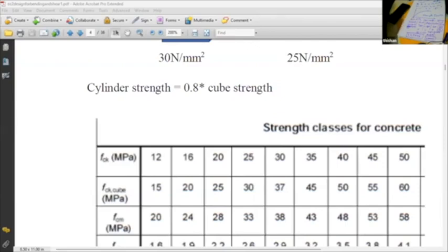Pre-stress concrete are thin sections, whereas reinforced concrete are massive sections. So in reinforced concrete construction, you can use fly ash, but even for pre-stress concrete, you can use fly ash to reduce the cost of construction. Because it gives a very nice finish with a very good cover zone that is resistant to chlorides and sulfate. So in highway bridges, it's worth using 15% fly ash, even with pre-stress concrete members.